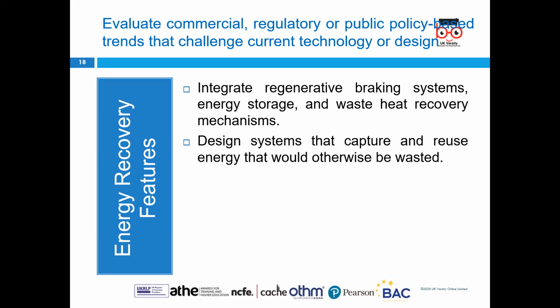Then the next trend, which has established current technology design, is energy recovery features. So the regenerative braking systems, where energy storage is being used, and waste heat recovery mechanisms are being used so as to recover the energy that has been produced during the motion of the vehicle. And then design systems that capture and reuse energy that would otherwise be wasted.